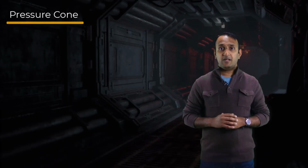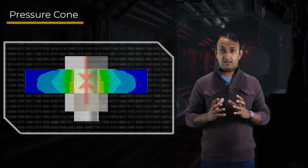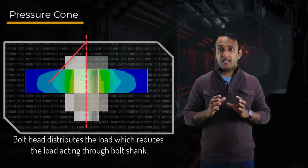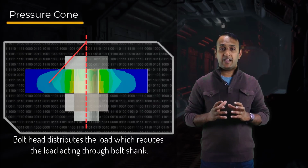One last thing to remember about the bolted joints is the concept of pressure cone. Under the compressive forces acting on the clamped parts, the stresses distribute in the shape of a cone, and this is called a pressure cone. The shape of the cone depends on the dimensions of both the clamped components and also the bolt specifications.